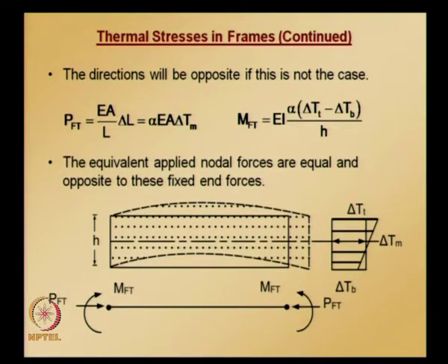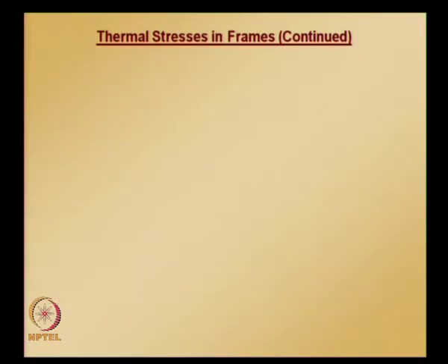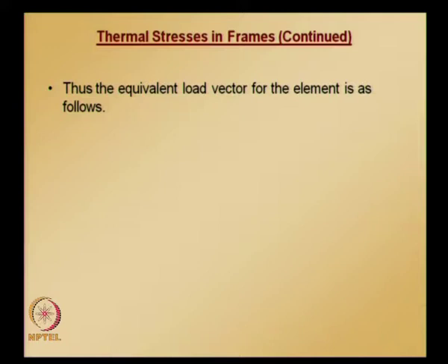Once we have this, equivalent applied nodal forces are equal and opposite in direction to these fixed end forces. So we can easily assemble the equivalent nodal force vector. This equivalent nodal force vector for an element is given by this.